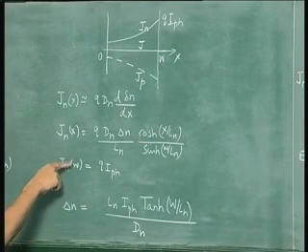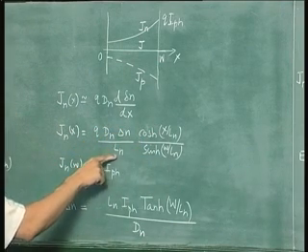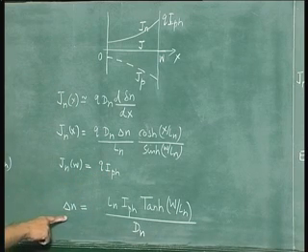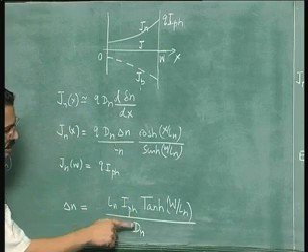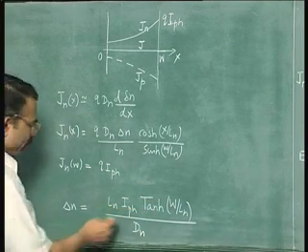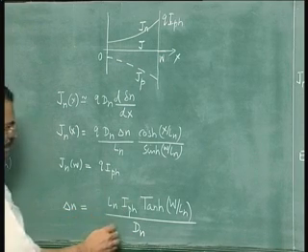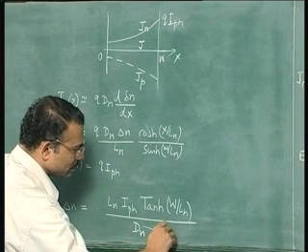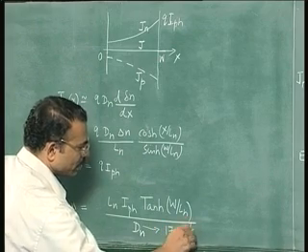Now you substitute x equal to W in this equation and then equate the result with this and solve for delta N, and the result will be delta N is equal to ln into I ph, the intensity of photons, by Dn into tan hyperbolic W by ln. Now we can evaluate delta N by substituting the various values. Dn, this is 17 centimeters square per second.